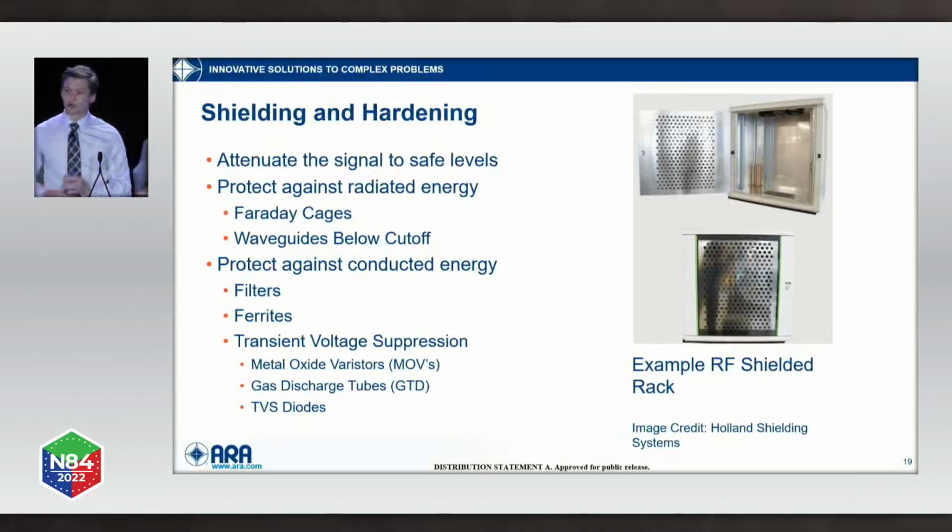So I'm sure a lot of you are familiar with the concept of a Faraday cage. It's a conductive enclosure that electromagnetic radiation cannot enter. An ideal shield would be, say, a hollow conductive sphere, but of course there are issues with this sphere, like you can't get anything in or out of it. You need a door, and for shielded enclosures like this, there are specially designed doors such that when it's closed, it forms a fully conductive seam around the door. Usually they're installed in pairs in a man-trap configuration, so only one can be opened at a time. Although that's not always foolproof. I've seen situations where people will override the system and prop open both doors because they're complaining they couldn't get a cell signal inside. It's like, that's the point.